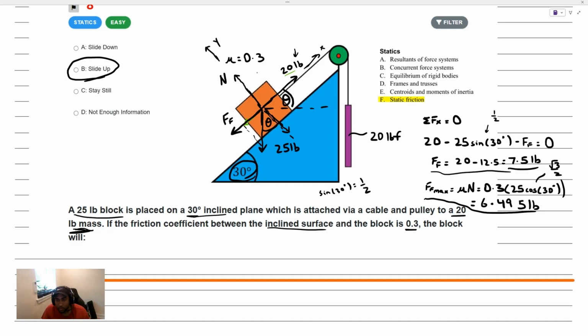So these friction problems are tricky, but just understanding the idea, think of that block placed on a table and the idea of the maximum friction force. Remember that the friction force is not the product of mu times N. That is the maximum possible friction force, and that friction is self-adjusting.